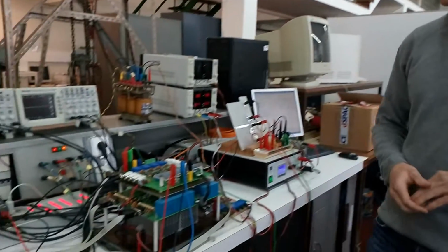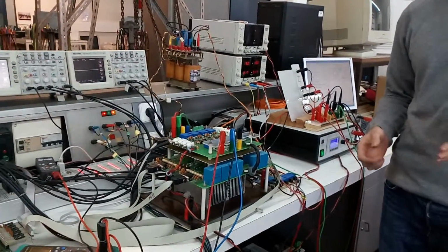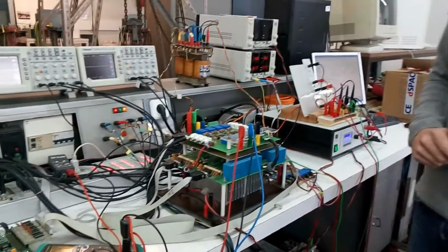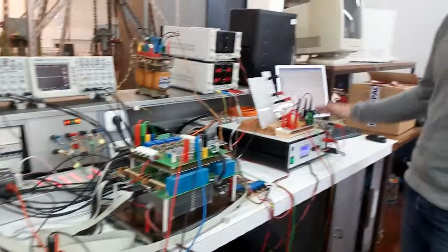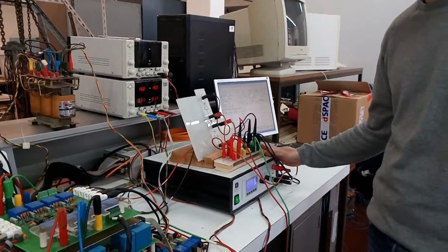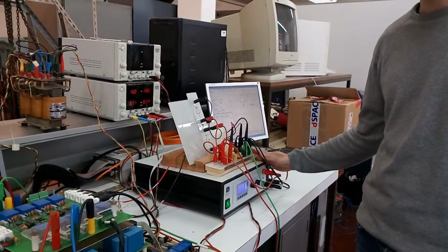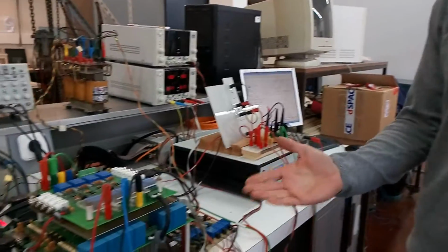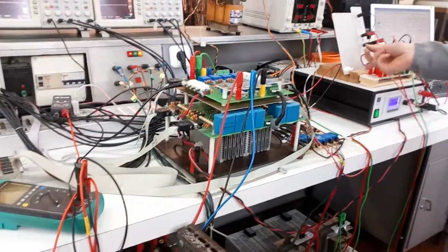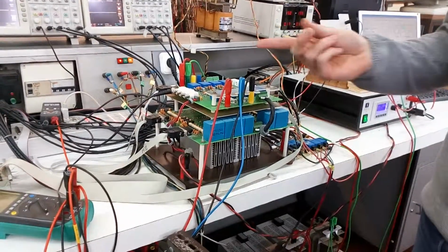Small demo of an equivalent photovoltaic system to work on the control of the converter, so we can try to improve the efficiency of the system and have a better integration on the grid. So the system is constituted first of a power supply that reproduces the equivalent characteristics of the PV panels and that injects power on the grid through the photovoltaic converter that converts DC power from the panels to AC power to be injected on the grid.